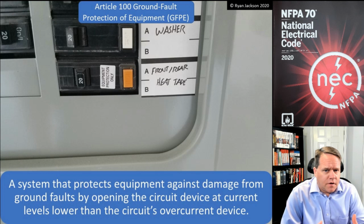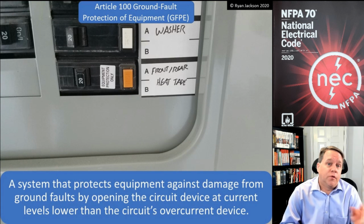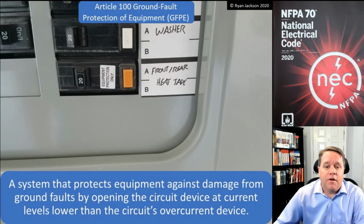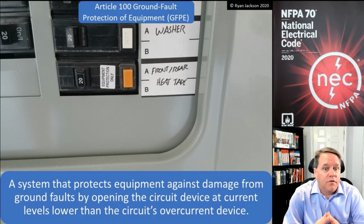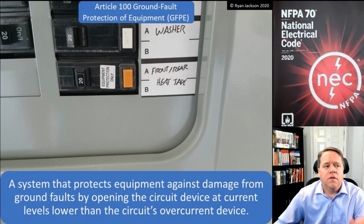We also have ground fault protection of equipment. Now, GFCI protection is for personnel, for humans. GFPE is for equipment. So ground fault protection of equipment is a system that protects equipment against damage from ground faults by opening the circuit device at current levels lower than the circuit's overcurrent device. Okay, so here in the photograph, we have a 20 amp circuit breaker, and if you can see the panel schedule, it says it's for the heat tape.